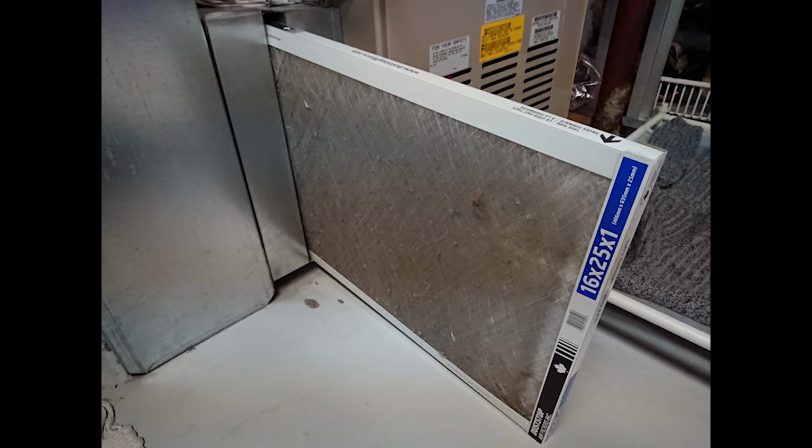On the side of our furnace, we'll also have our filters. They are placed on the intake side of the blower. Their job is to remove dust and particles from the air before the air enters the furnace. This is the one maintenance item that we need to make sure that we are maintaining properly. Replace it every 3 months because if we reduce the airflow to the furnace, it will not only reduce our efficiency, but it could also cause premature degrading of our furnace components.